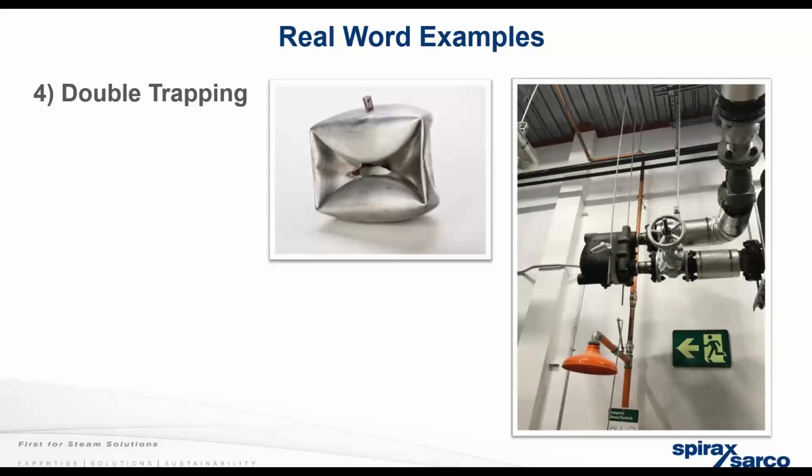I can't see it on my screen, but hopefully you guys can see it on your screen. There's a big F&T steam trap on the right-hand side there. Well, that F&T steam trap was piped perfectly, had a nice strainer, nice isolation valves, et cetera, except that it was after all the process equipment steam traps. And basically, if we look at steam traps as liquid level controllers, it was trying to maintain a flooded state in the entire condensate piping system upstream of the steam trap.